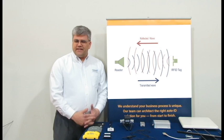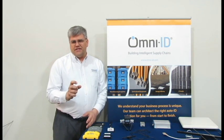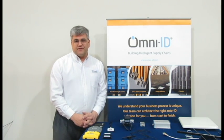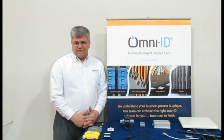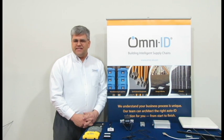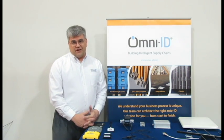The difference from a radar wave hitting the metal and coming back is that the modulation that the chip performs on the wave is decoded into ones and zeros, and that allows us to read an ID, sometimes sensor information or other useful things from the device. Because passive has no inherent power of itself, it's merely being energized and modulating a waveform, it tends to be useful for relatively short distances, but it is very, very cheap, and it is very effective for tagging many, many items. There is another technology though, and we call that Active RFID.